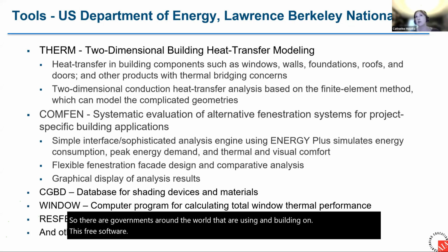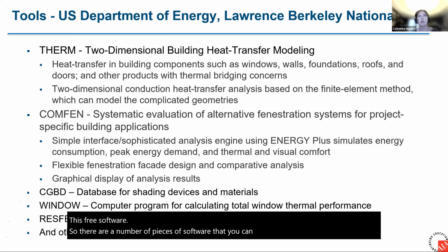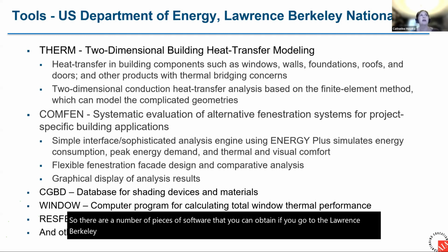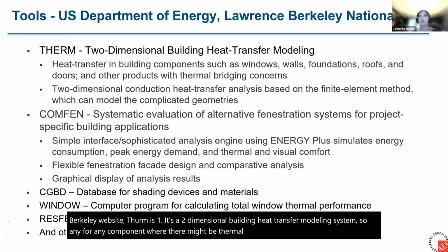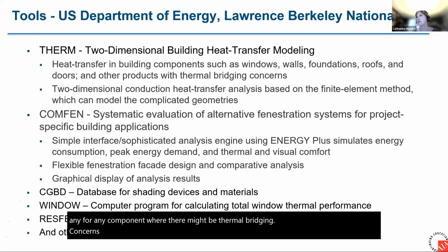There are a number of pieces of software that you can obtain if you go to the Lawrence Berkeley website. Therm is one. It's a two-dimensional building heat transfer modeling system. For any component where there might be thermal bridging concerns, you can use it to make an assessment.